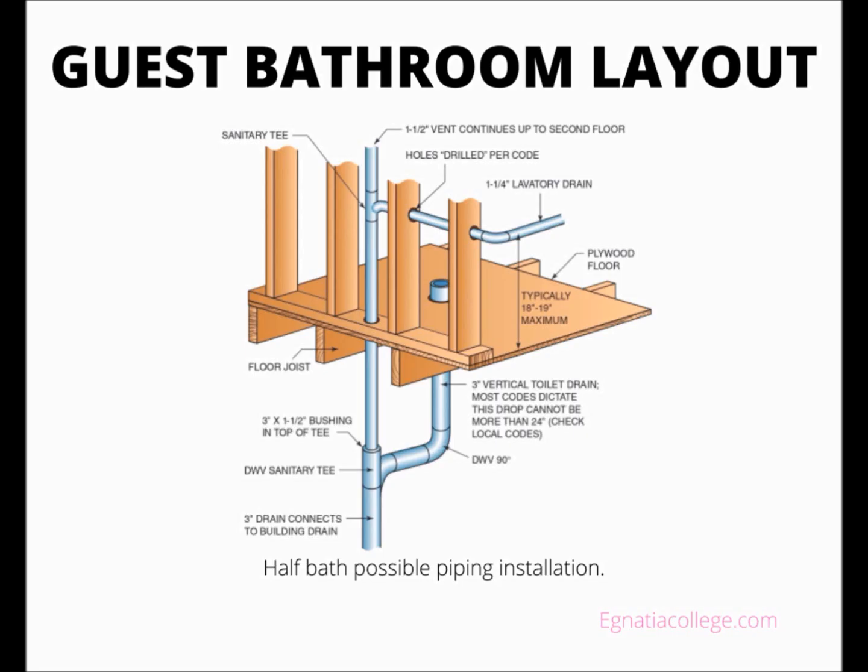The stairwell wall continues through the floor above, which means that it might be possible to route the vent pipe vertically up to the attic. If the vent cannot be installed in a continuous manner in a wall, it can be routed within the second floor joists.